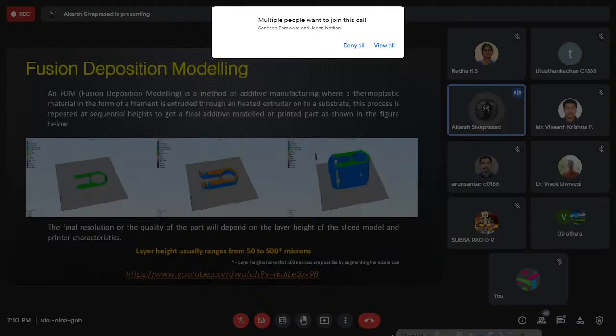heated filament which is being deposited, you have certain restrictions on the size and the resolution that you can print at. Usually for FDM, the layer height is roughly 50 to 500 microns, depending on your gantry. If you have a precision linear motor gantry, you can take it down to 50 microns. But that again depends on your plastic material and its thermal expansion and all those material properties. Because if the material expands too much or contracts too much and creates warp, it's just going to fly off the build plate. You can't print anymore. It just fails mid-build.